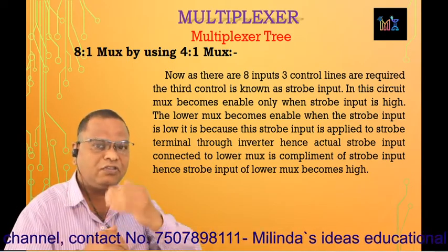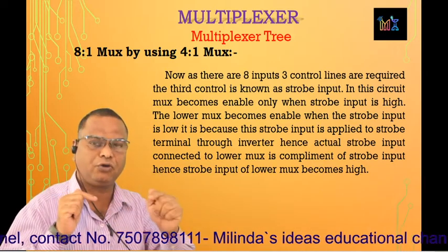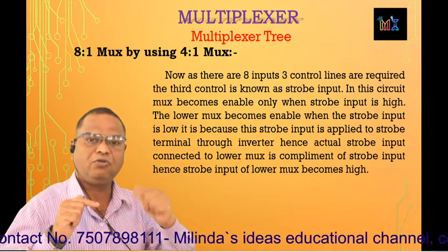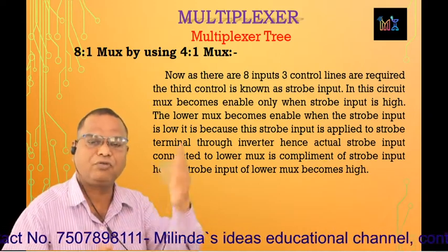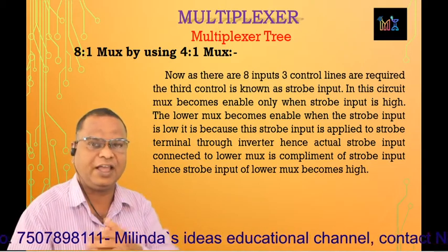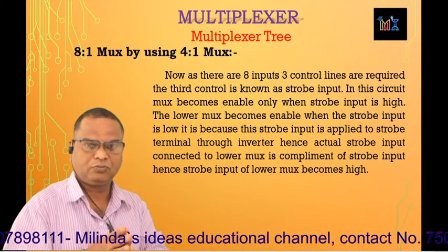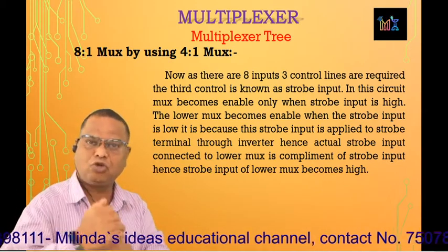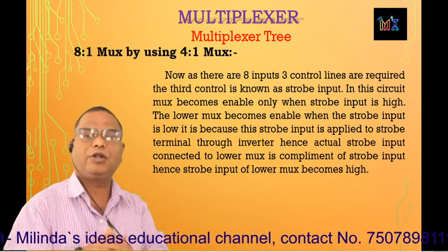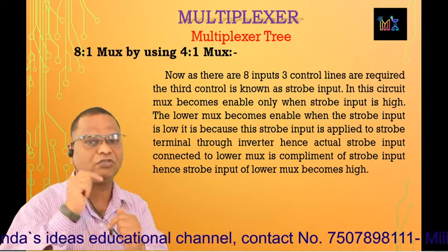But after 0 1 1, the control inputs now become 1 0 0, the next 1 0 1, next 1 1 0, and the last one is 1 1 1. As the control input S2 is high, the strobe input of the lower mux goes to low level, because it is connected through a NOT gate. So the output of the NOT gate now becomes low. But as the control input S2 is high, the upper mux is in enable mode because its strobe input is high.